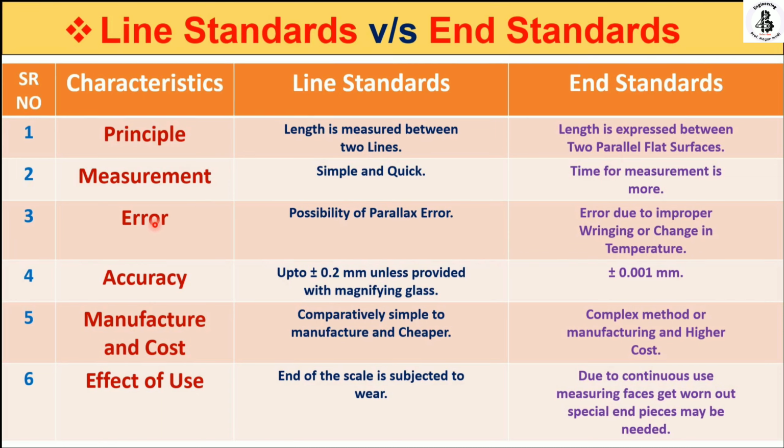Third, characteristics with regard to errors. In case of the line standards, there is the possibility of parallax error, which is generally the reading error. So your reading should always be at right angles, which is the most preferred position to take the readings.